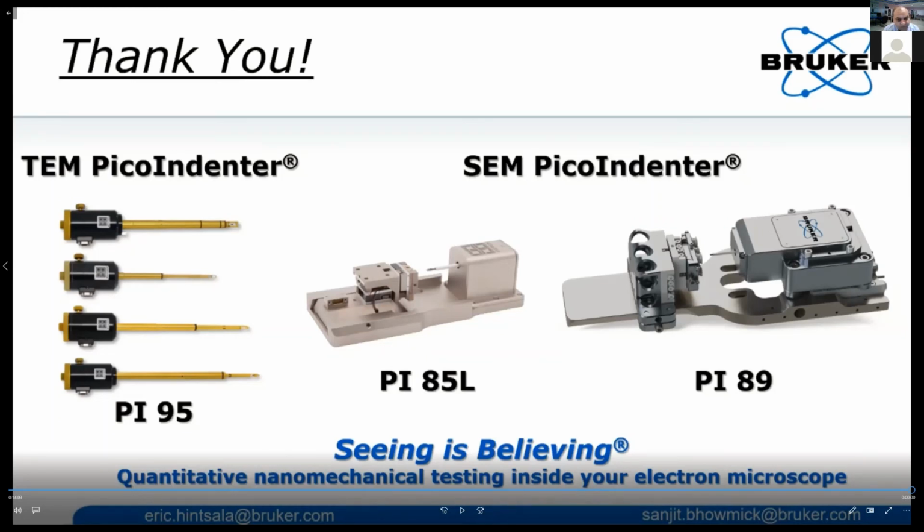The load-displacement curve itself will show clearly that difference. But when you do this deformation, the deformation mechanics also changes. For example, if you have compressive stress, it will pile up. When you have tensile stress, it will sink in. So when you try to calculate the hardness, it does not remain the same. There are ways to extract the residual stress, but you can do that qualitatively. In the olden days, people used hardness testing as a way of measuring the residual stress. You can do that, but you've got to be careful.